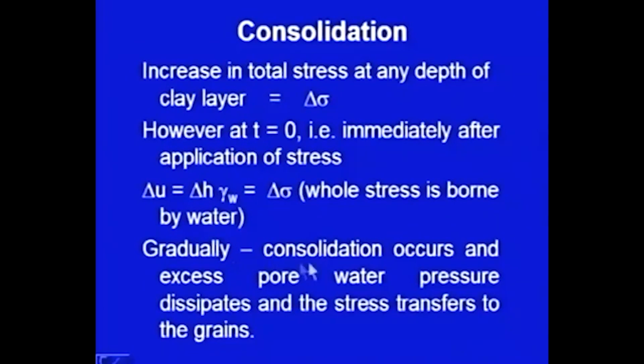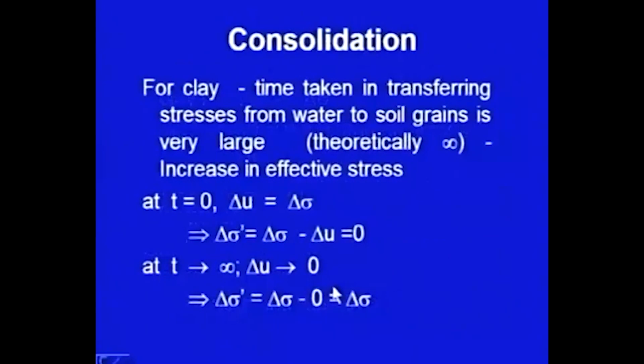Gradually the consolidation will occur, this excess pore water pressure will dissipate and the stresses will transfer to the soil grains. Theoretically, the time taken in transferring these stresses from water to soil grains is very large. Theoretically, it is infinity.